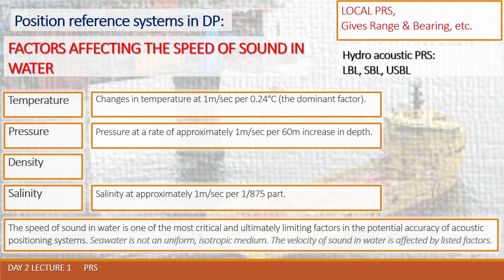Then a special calibration file is created to determine the speed of sound in water in that specific location, and this calibration file should be provided to the fleet which is going to use the HPR equipment in this area, and this file must be downloaded to your HPR station. Otherwise, the system will not be able to produce correct calculations.